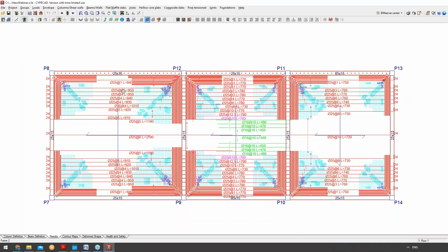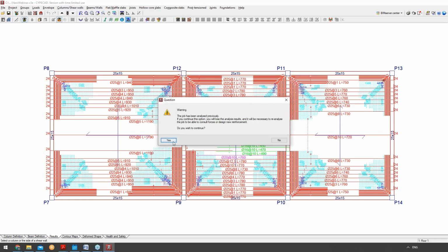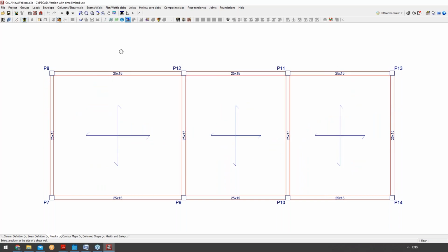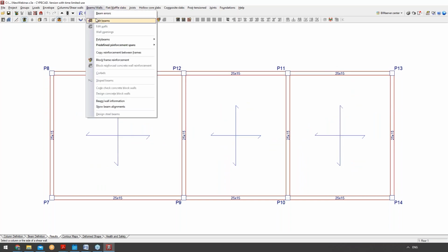Now, of course, I didn't actually look at the different loads and different types of sections that I've inserted. You can see I have inserted quite small sections, and before I introduced 2 kilonewton live and dead loads as well. But basically, the point of all this is to look at how we can edit these columns and beams. So coming into here, column and shear walls, I can edit. Let's go into this particular column, oh, 1 second, into this beam, sorry.